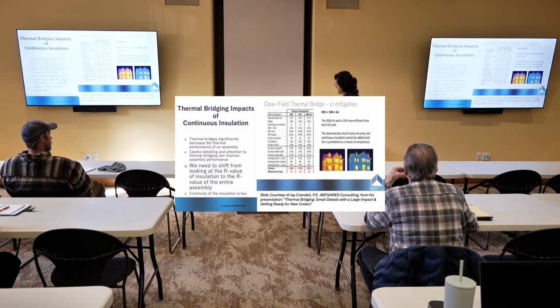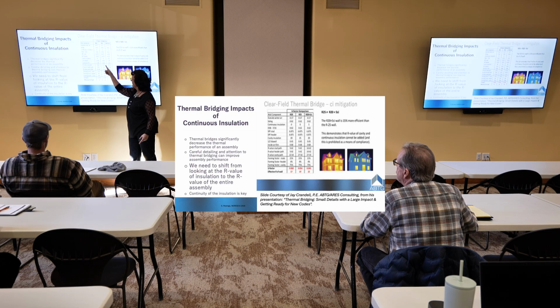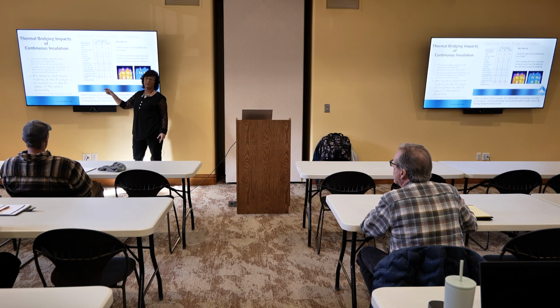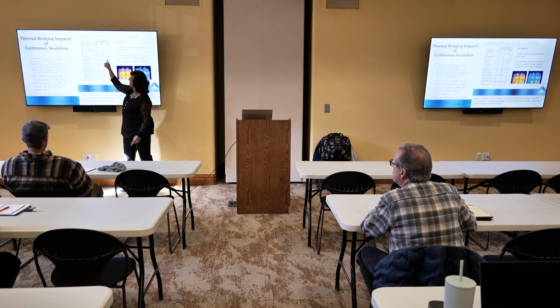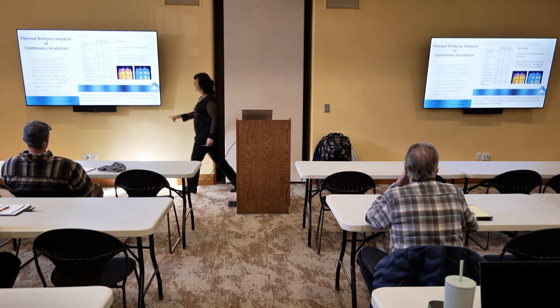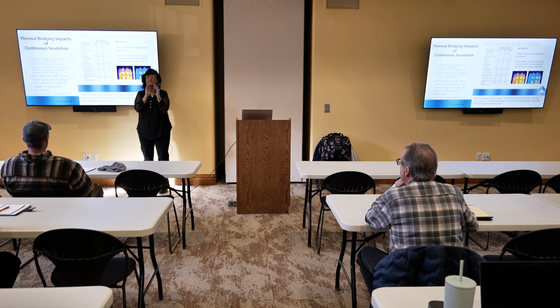They're different, so you can look at this formula here. If I go through all the layers of this wall, an R25 wall gives me an effective R value of R19 when I'm all done. An R20 plus 5 gives me an effective R value of R22. Right? Because I have more continuous insulation, I don't have as much thermal bridging. This R19 reflects the fact that I have thermal bridging there because I have those metal Z strips, with only cavity and cavity. I don't have any continuous insulation.